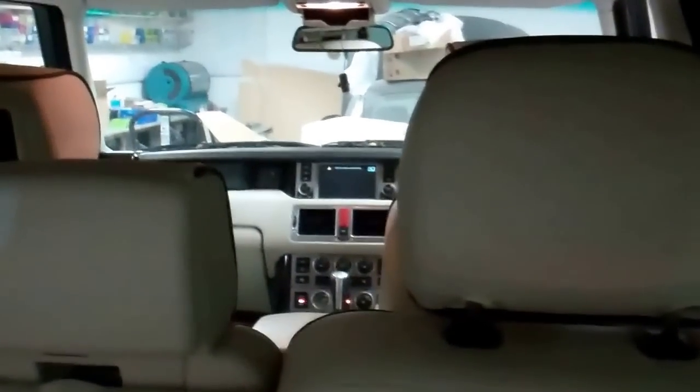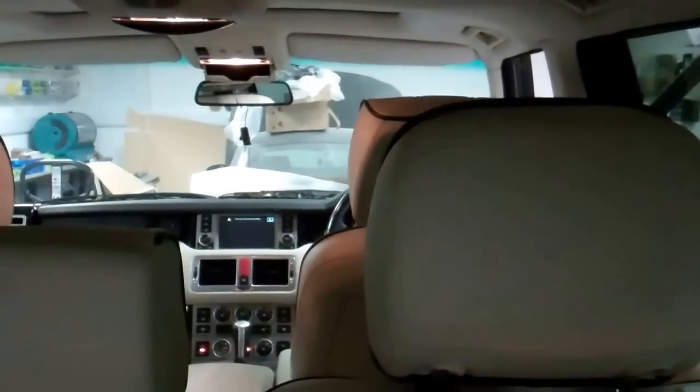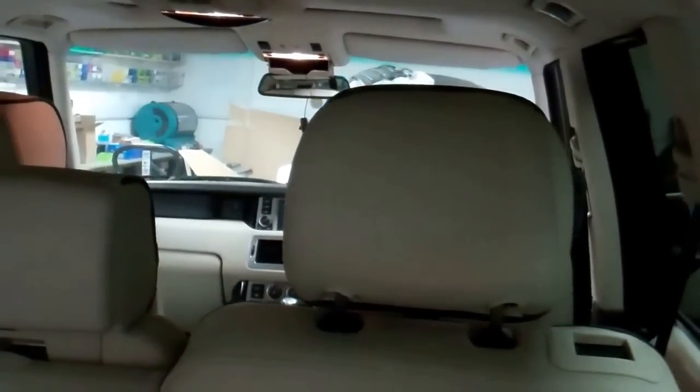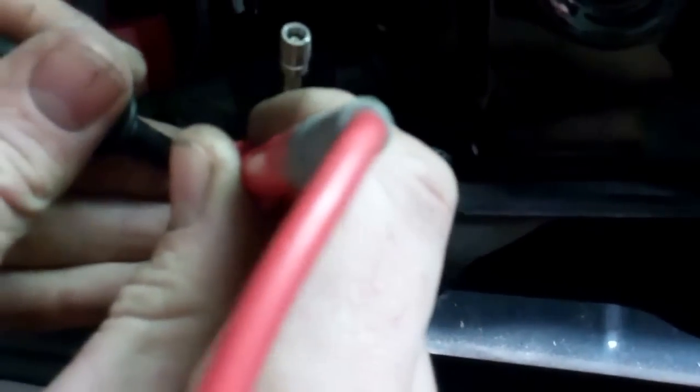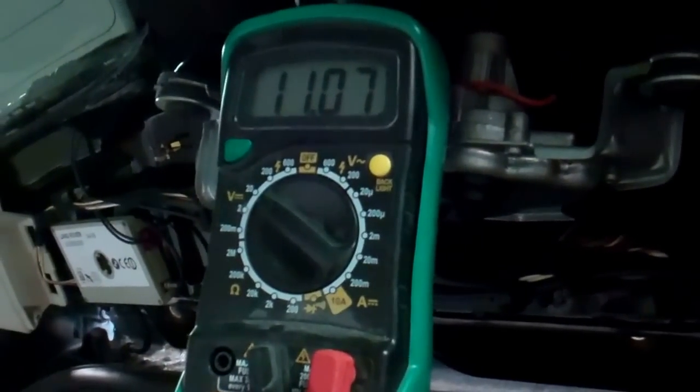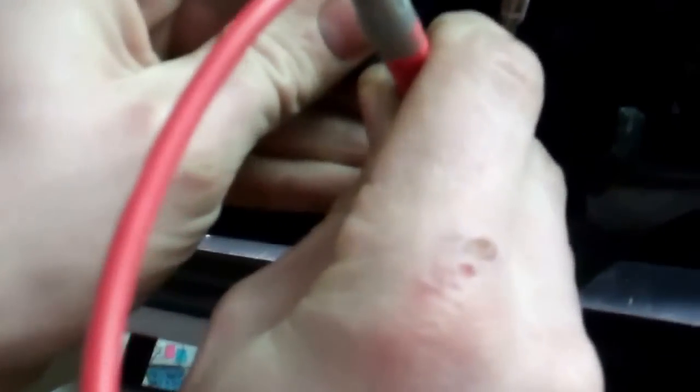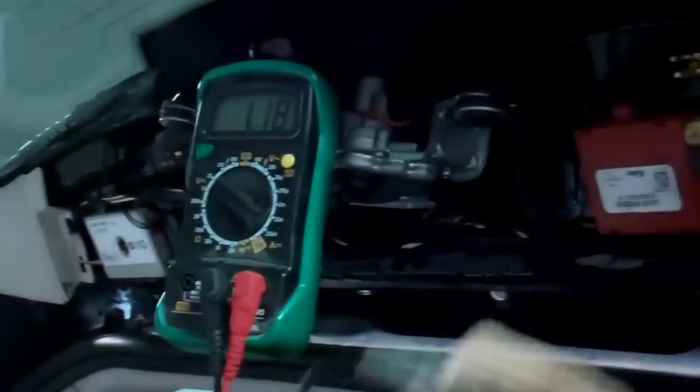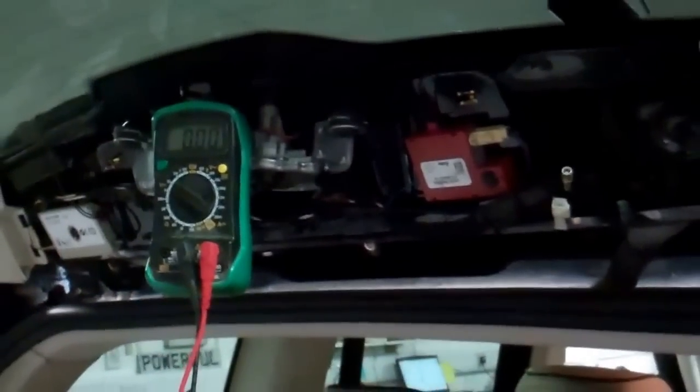We've put it in reverse, you can probably see on the screen there, can you? There we go, yeah. We've put it in reverse, we've put the ignition on, we've got the screen saying careful, and just as fault finding, we're going to check on the 2 pins that we've got voltage. When we're in reverse we've got 11 volts. So there's voltage coming up to the unit, so that's one good check done. Check there's no fuse or a wiring problem.